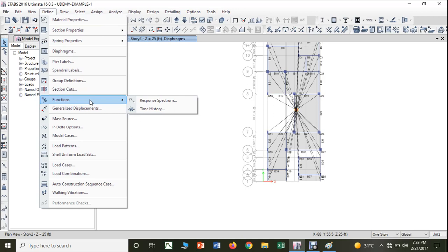That is what we call static analysis. Doing the static analysis is very easy because we assume that the loads on the structure will not change. They are going to remain constant over a period of time. So that design is very easy.